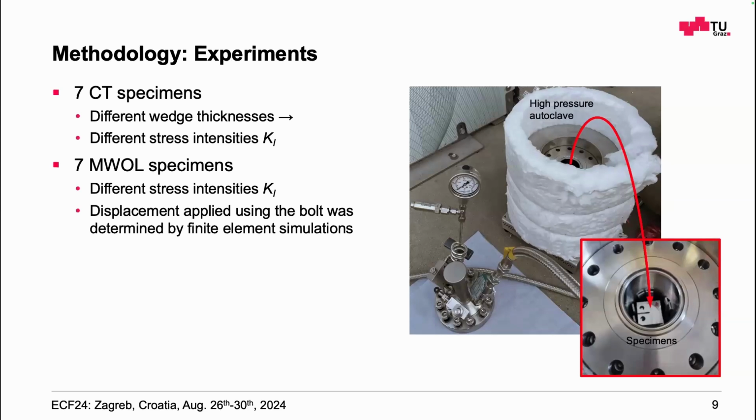What you see here, also interesting, is that such a small autoclave allows us to increase the temperature. In our case, we can go to pressures up to 500 bars, for example, and to temperatures of about 500 degrees. So these are really conditions which are similar to industrial applications. And I have to say, the charging in gas atmosphere is completely different to electrochemical charging, for example, as most are doing, but I think you know this.